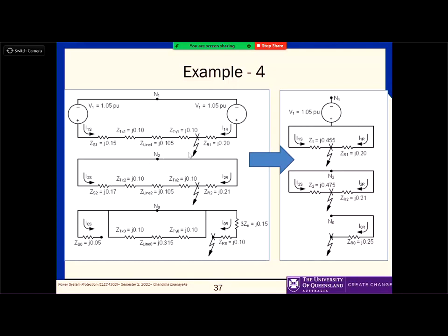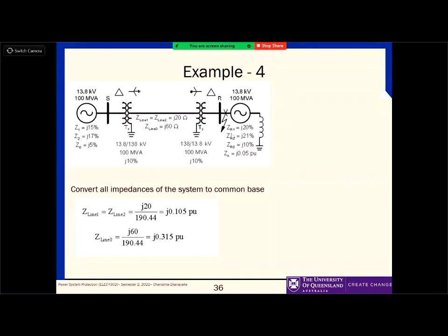Now, if you are looking at negative sequence, again, from this point to here, and from this point to here, you have two separate networks, right? Right-hand side, if you go back, it is not clear. Right-hand side is the connection from this point to the generator to the ground. Left-hand side of that network is from this fault location to the transformer, through the line to this transformer to the generator.